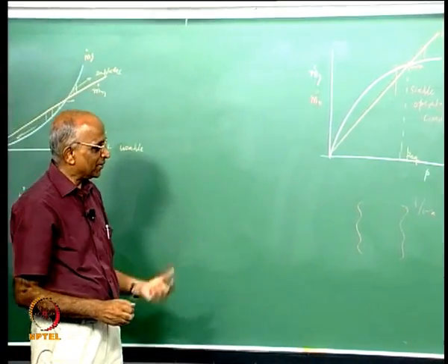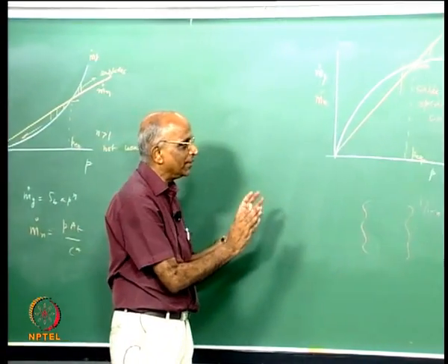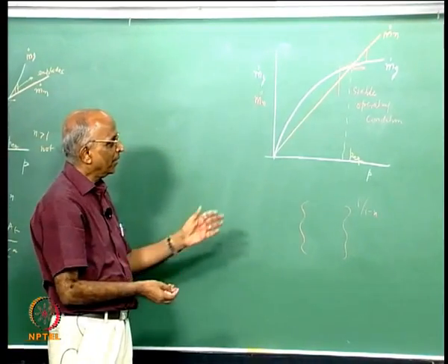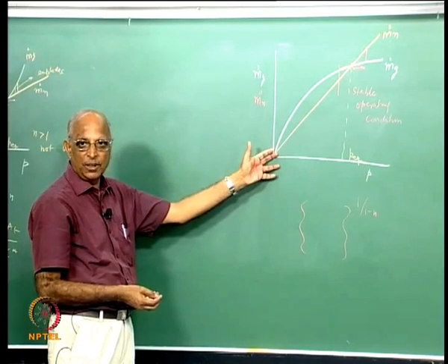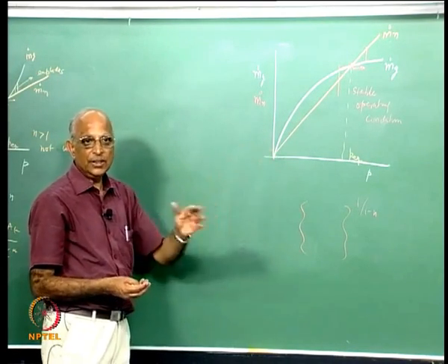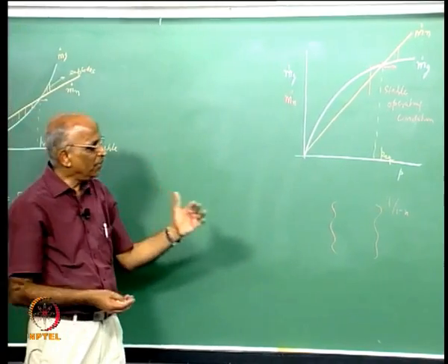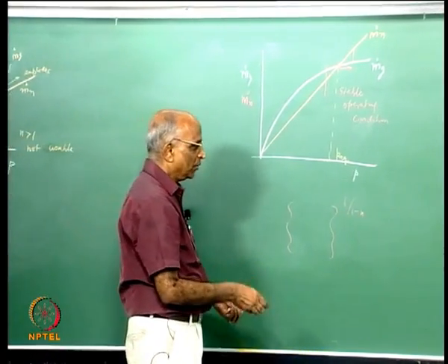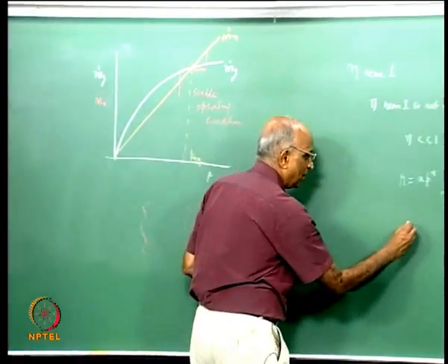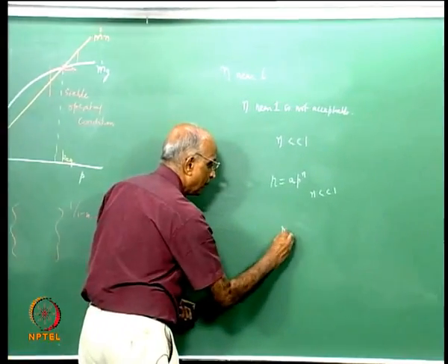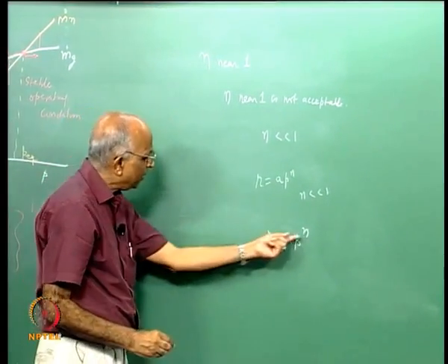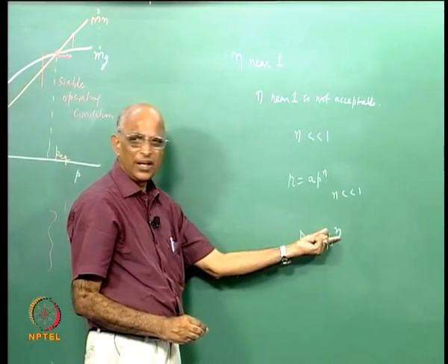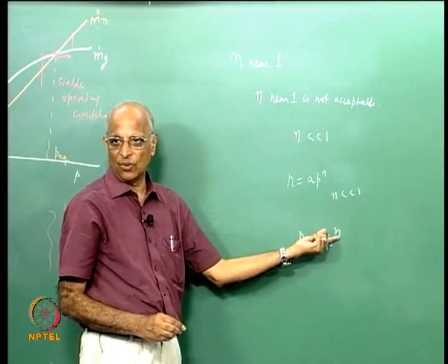I will continue with this in the next class, but what we did in this particular class was we derived an expression for the burn rate of composite propellants using the standoff distance x. We found that it is still modelable using the Saint-Robert's law, namely r is equal to a P to the power n. We related it to a rocket and we said, well, n must be very much less than 1.